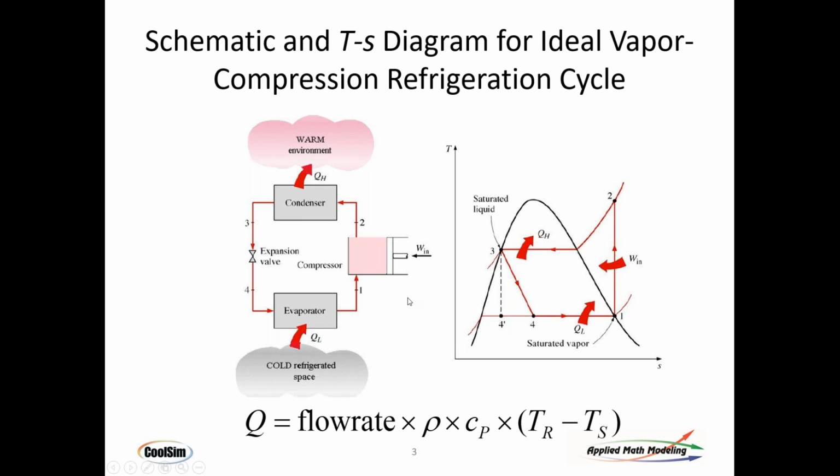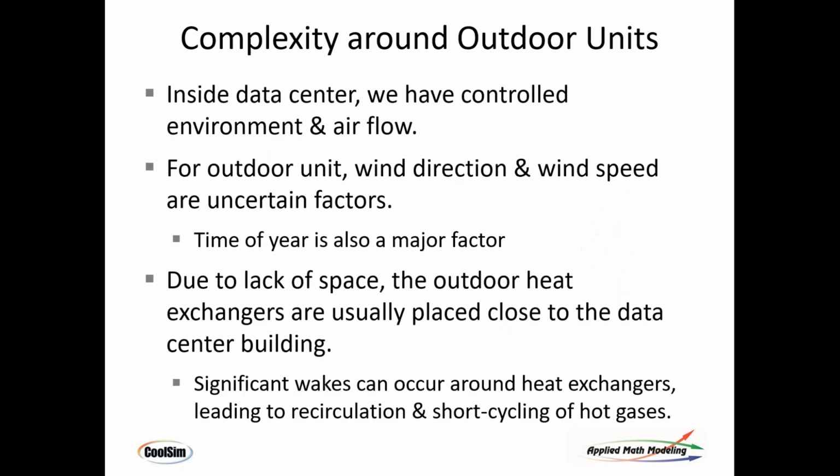then you're going to have poor performance and your ability to dump heat is going to decline, and that leads to cooling problems. So I wanted to just put this up and remind you that this is what we're talking about. I wanted to remind you of this equation because if you can keep this in your head, it helps a lot. Essentially, heat transfer is correlated very highly, almost linearly, to mass flow rate and delta T. You've got to have one or the other or both in order to get good heat transfer.